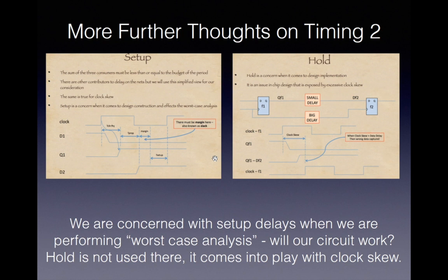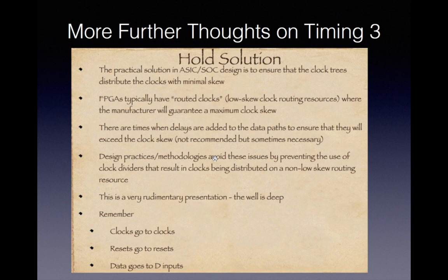We rely on our tools to ensure that we don't have this situation, and we assist the tools by only using the clock trees to clock our flops. This is why I insist only clocks go to clocks. Here, I think you can read this yourself. Nothing new.